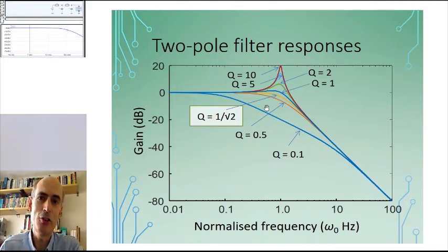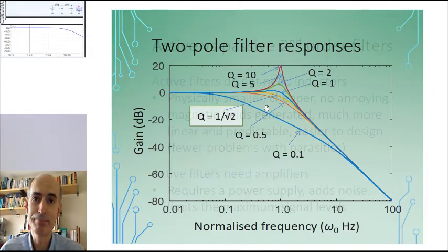And inductors are best avoided if you can. They are expensive, and they're difficult to work with because they have large parasitics. Real inductors don't behave much like ideal inductors at all. They also tend to be non-linear. So the value of inductance that you get is a function of the amplitude of the signal that's passing through.